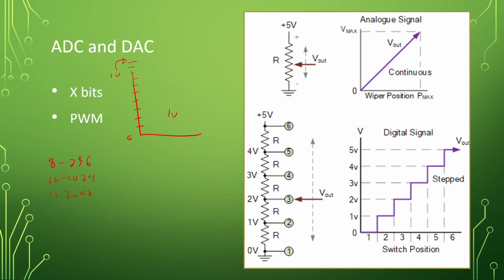So even if that sensor is putting out a 0 to 10 volt analog signal, it could be anywhere between 0 and 10 volts. It could be 8.362 volts. You're only going to be able to read whether it's 8 or 9 volts in that case. And you would probably write, oh, that's 8 volts. All right. So that's not giving you a lot of resolution.